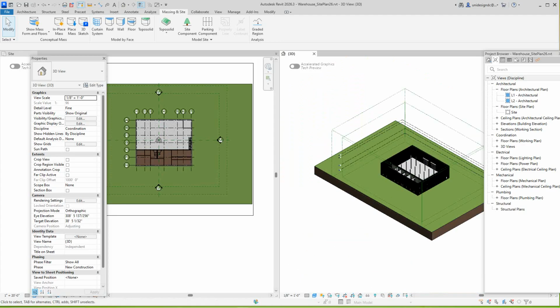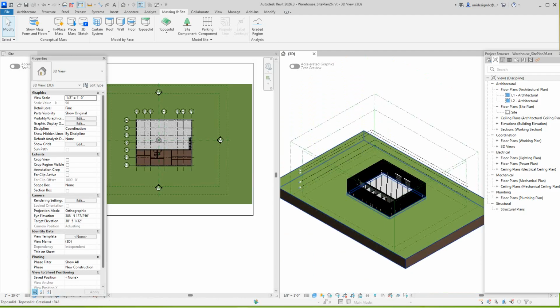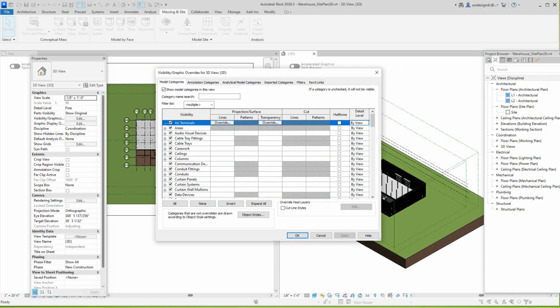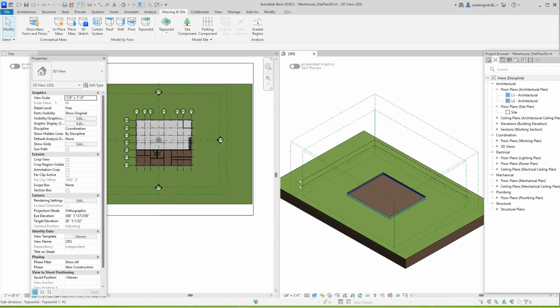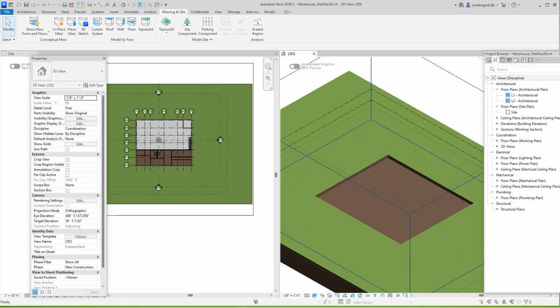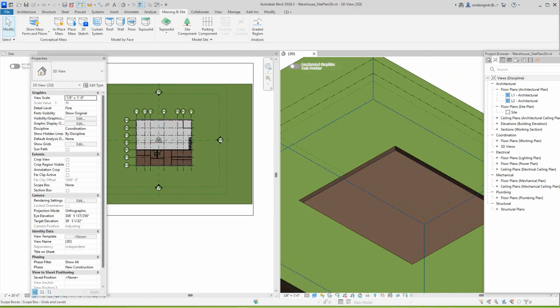Actually, let's do a building pad for this, because normally we have one and we don't have it in Revit 2026. We've got these new features, so I'm going to Revit Links and shut this off again. Okay. Now I'm going to draw another pad here. Let me see, this is at 42 inches.